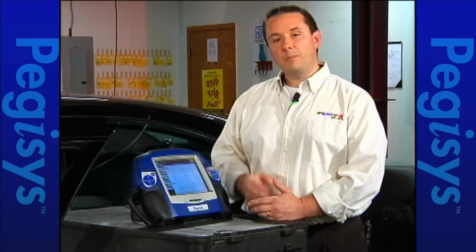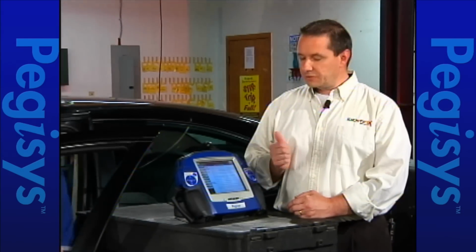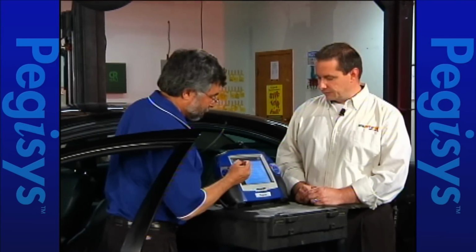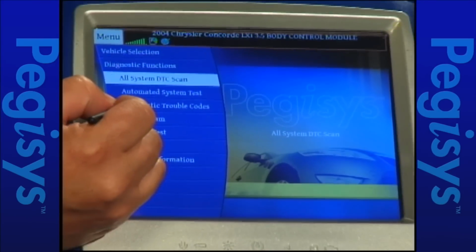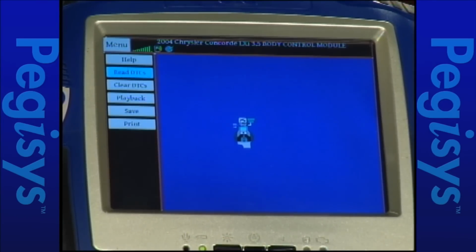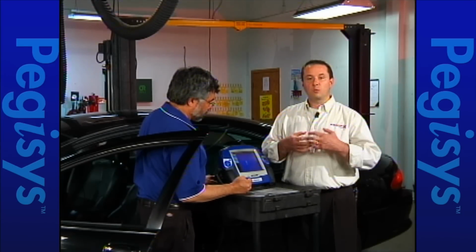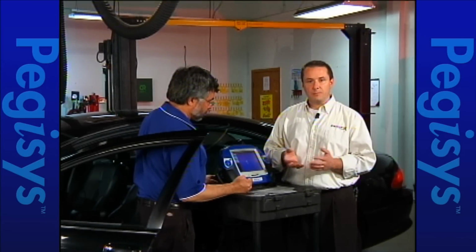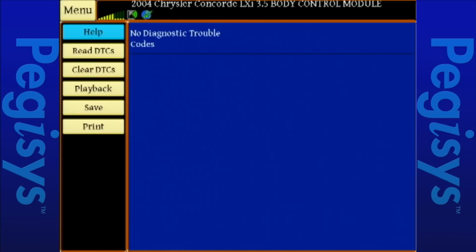Well, 5 minutes have gone by now with the vehicle running. So I think what we're going to be doing is rechecking the body computer for trouble codes. That is our next step. And Steve here is going to do that for me. So what has happened now, while we've had the car running, is the body computer has been recalibrating the whole climate control system. We'll take a look here. Hey, we've got no diagnostic trouble codes.